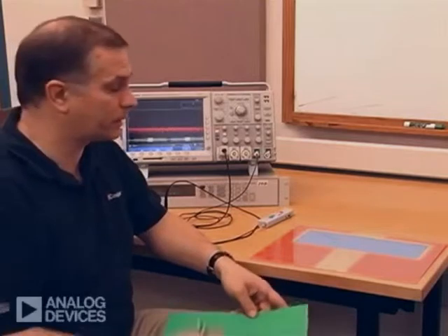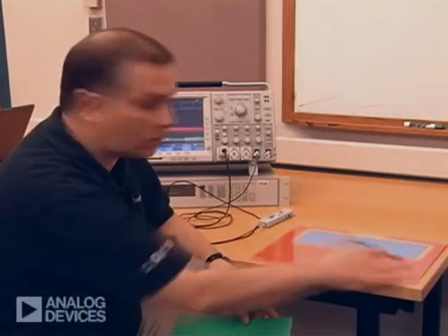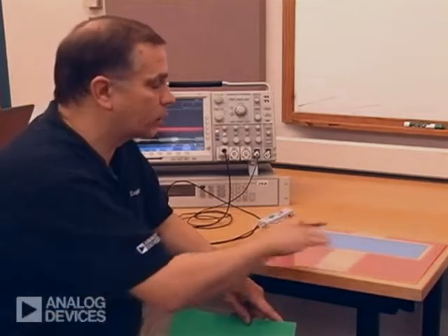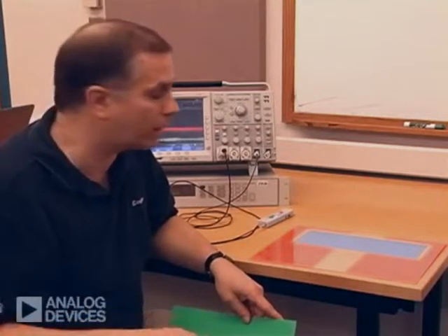Now let's address the problem of radiated emissions from signals being driven from a primary to a secondary across a gap. As I said earlier, the way that we found that shorts out that dipole is to add capacitance from the secondary to the primary. It has to be very low inductance, and it also has to be buried in a central layer of the circuit board in order to maintain the creepage and clearance of the entire board. Structures internal to the board can span isolation gaps, especially for basic insulation. There are no minimum distances required.